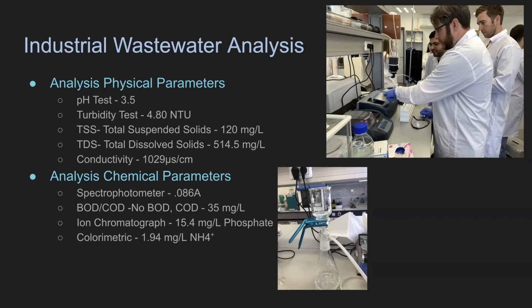We didn't find any BOD, or biochemical oxygen demand, but we did find a small amount of chemical oxygen demand, or COD. This was expected as our sample was from a metal finishing plant and not municipal. Next, Myke will talk more about copper and our treatment method.